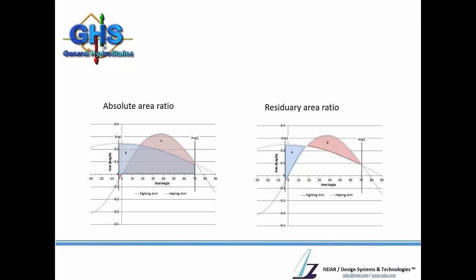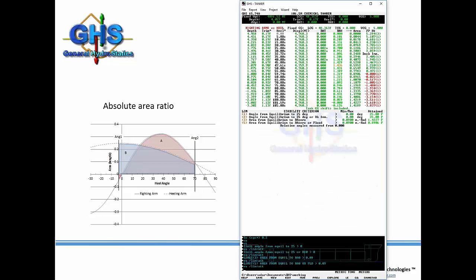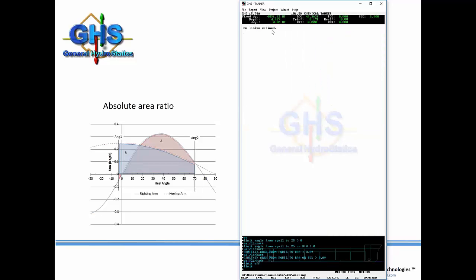And perhaps better than that, I will just show quickly what this setup would be. Okay, let's use the same model, but I will just erase the existing limits. So I would just push limit off. That would erase the existing limits. If I type limit, it will tell me that there are no limits defined in the model.